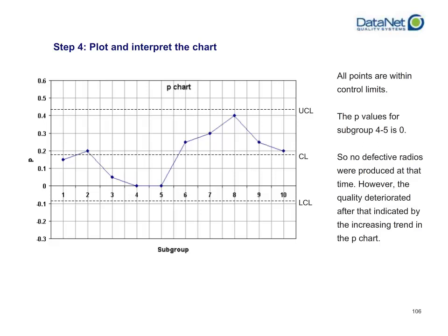So we've gone ahead and plotted the solution, the graphing of the control chart. Now we can't absolutely know what was going on here, but we can make some inferences from what we see. It is your job as a quality expert, a quality engineer, to go in and actually begin to investigate what you see here. The lower control limit was less than 0, meaning we would expect that getting no defects is within historical norms or is normally distributed data. Your upper control limit is at around 40%.